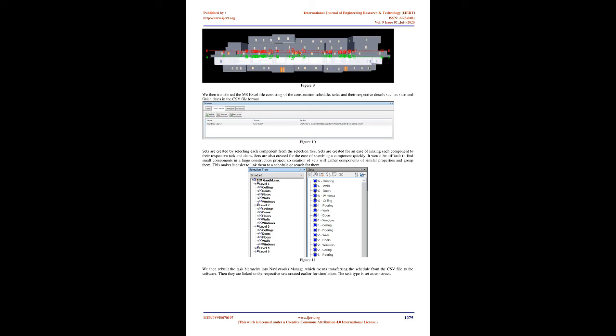The main application of Revit software is creating the three-dimensional model of the building and all its components, structure to even the furniture. We first made grid lines that could be used as reference while drawing the floor plan of each floor. The grid line mainly outlines the outer walls of the ground floor. This helps us use a reference point in the space dimension to find the exact position of walls in the higher levels. These grid lines are reference points and do not have direct involvement in the 3D model description. The grid line is used only as reference for two dimensions such as length of the room and width or breadth of the room. It does not become a reference for height of the floor or room.